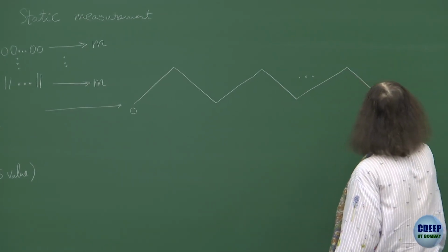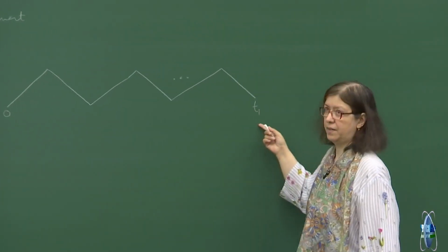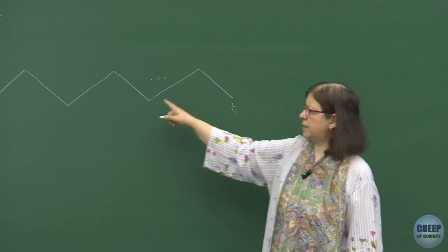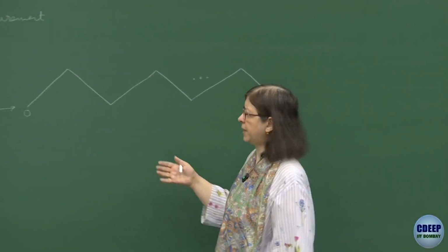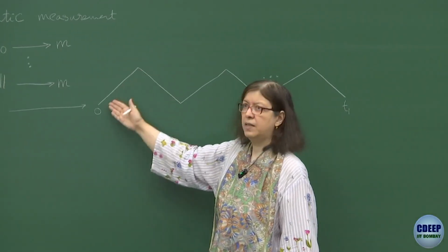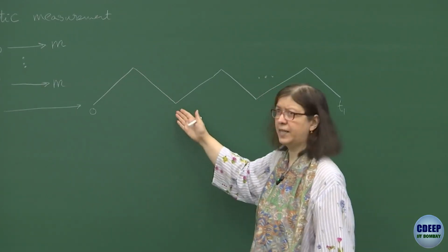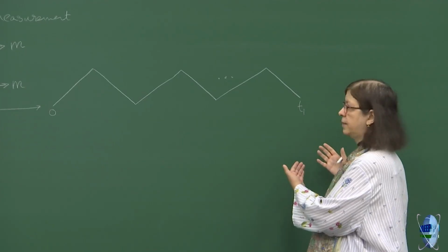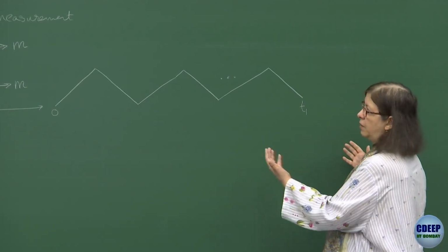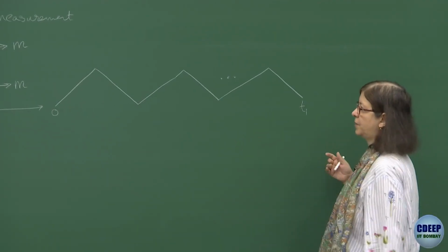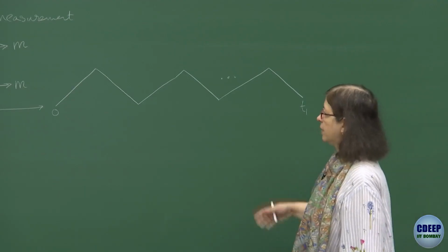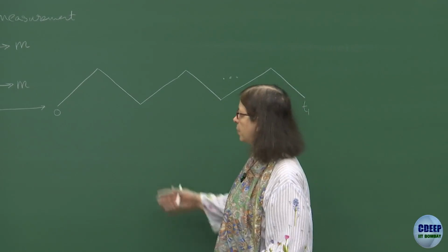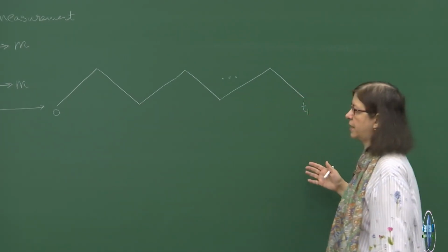So in fact, t1 now will be much more than the t1 that we had there, considering the number of cycles. And keep in mind also the slope of this ramp, rising ramp and falling ramp, both is very low. So therefore, it will take reasonably long time as compared to the actual speed of the ADC. Because this is going to be a static measurement, this m will be more than 1 depending on the number of cycles.